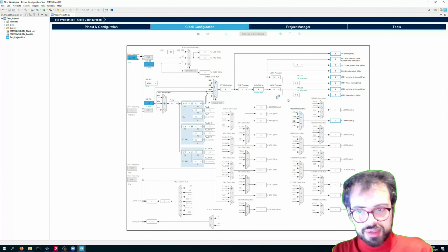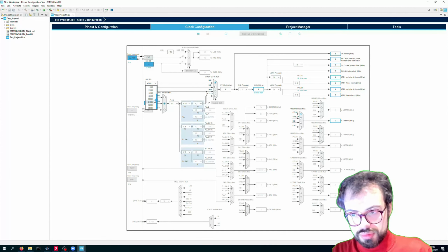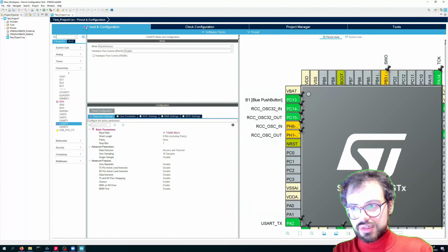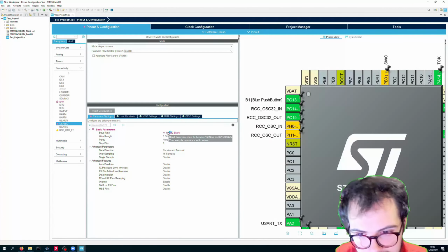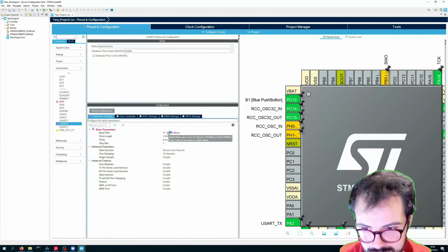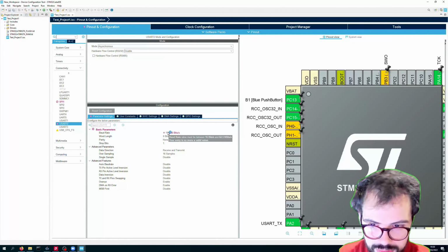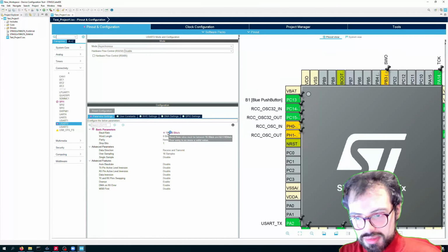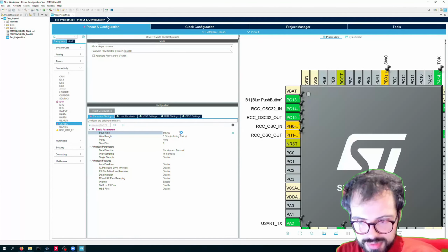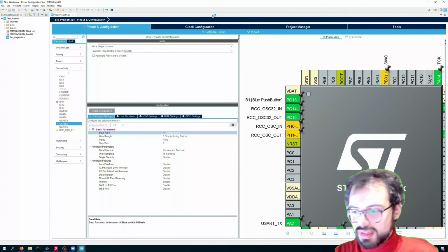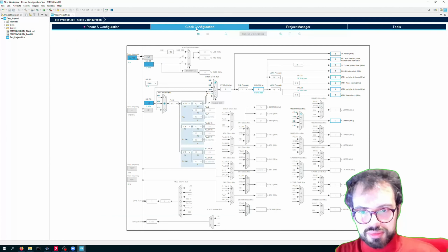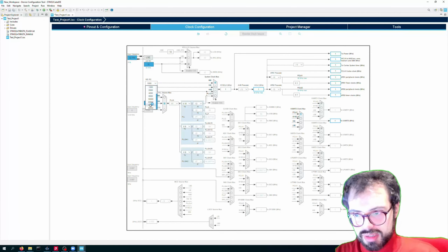So if I go to 1 megahertz, there is an X here, and here it's saying that it's not possible, it must be maximum 65 kilobits per second, so it knows in this case. So if I change it, it will be fine, but I'm going to keep this value because it's the default one, and I don't care too much. We can put 4 megahertz.